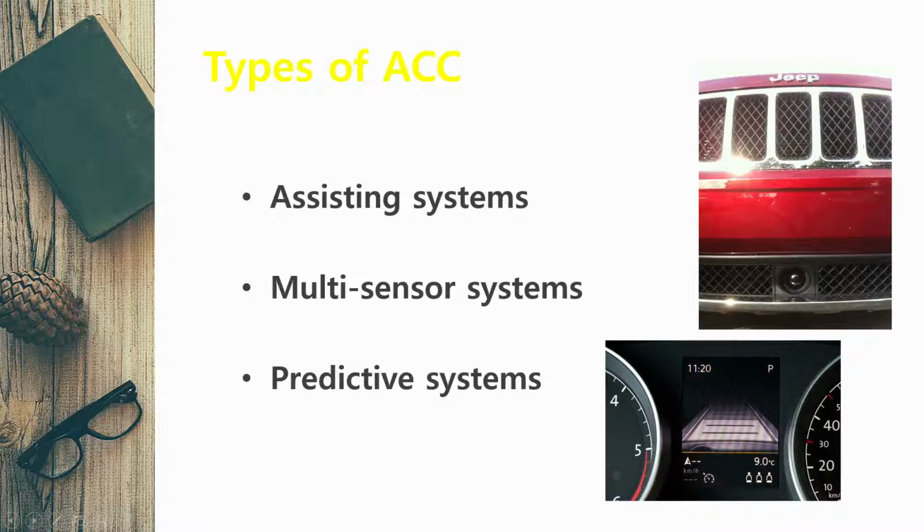Assistance system is a radar-based ACC, often featuring a pre-crash system which warns the driver and provides brake support if there is a high risk of a collision. Also, in certain cars, it is incorporated with a lane maintenance system which provides a power steering assist to reduce steering input burden on corners when the cruise control system is activated.